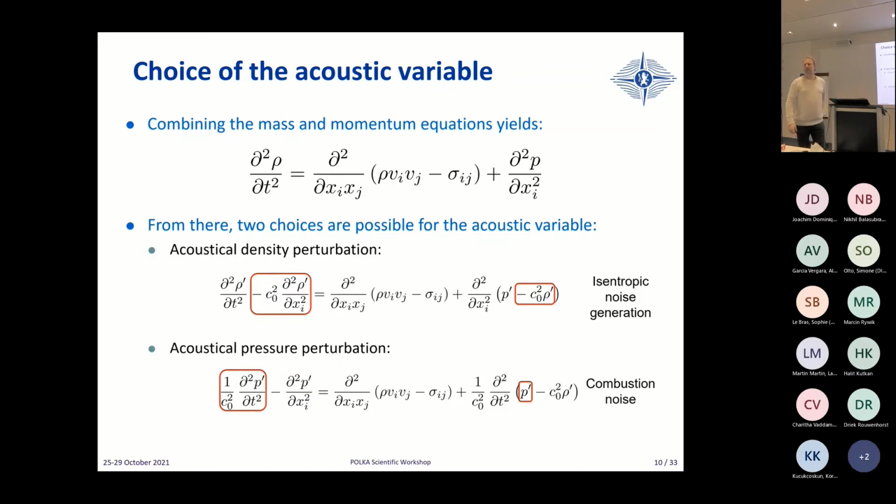If you are convecting hot air in a cold air surrounding through a nozzle, you have only dipole. But if you are convecting an entropy wave of combustion product, the gamma of combustion product is usually much lower, it can be 1.1, 1.2, something like this. Depending, but 1.2, 1.3 would be common. Okay. So there is a contrast in the gamma. That's the full correct answer.